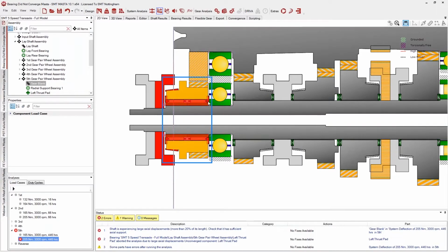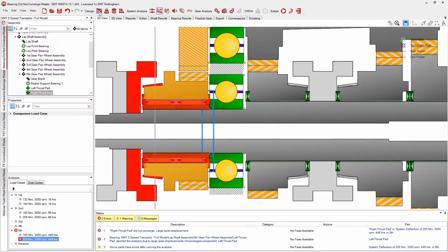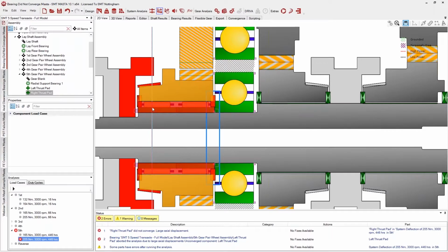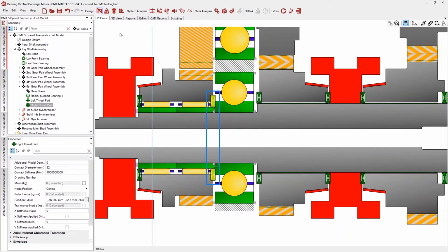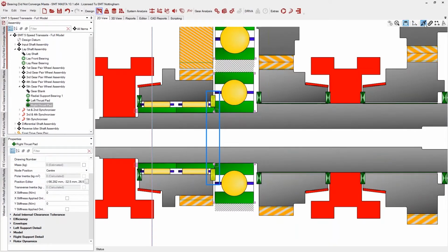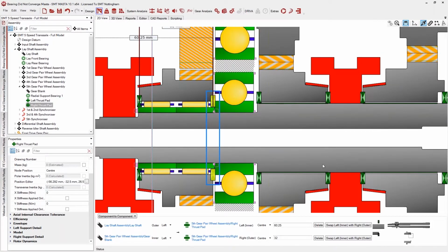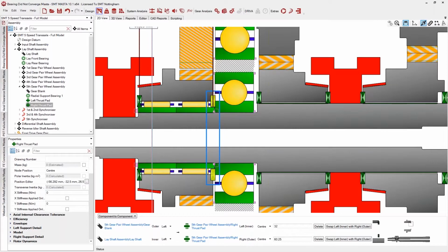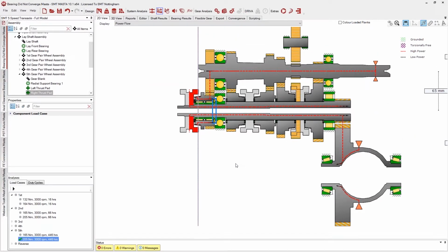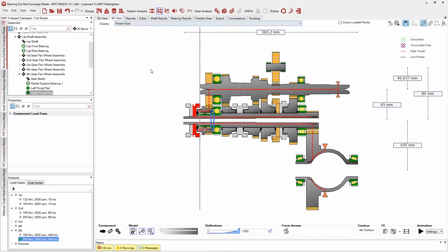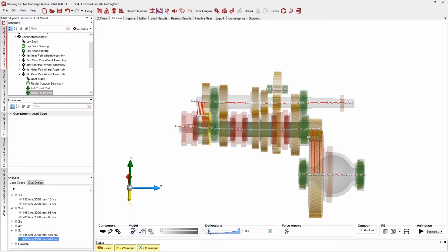So what we have here is the axial clearance bearing. As there's no axial support in the needle roller bearing, we can go into the move component or the connect component tool. And there's a function here just to swap the inner with the outer, so you don't need to go connecting it all over again. And you can see now that we've swapped it, it's happy with that, and we don't have anything flying away.